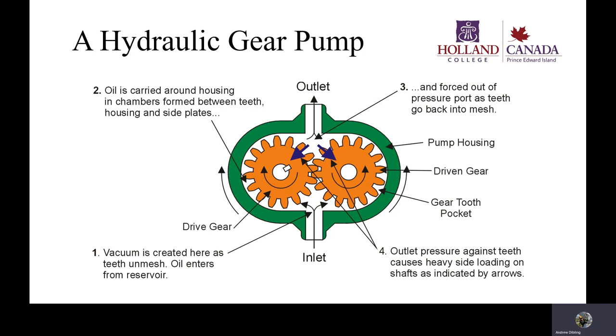You've got two shafts, you've got two sets of cog gears. You're looking for wear in the housing, wear on the teeth, wear in the bearings, and that's about it. And wear will tell you a lot about the health of your system. If I have wear on the inside coming into the pump, is that wear from age and neglect, or is that from contamination in the fluid itself? So this will tell you, just like a bad heart in a person, a lot about the underlying health of the machinery. And that's where, as a technician, you are really most valuable.